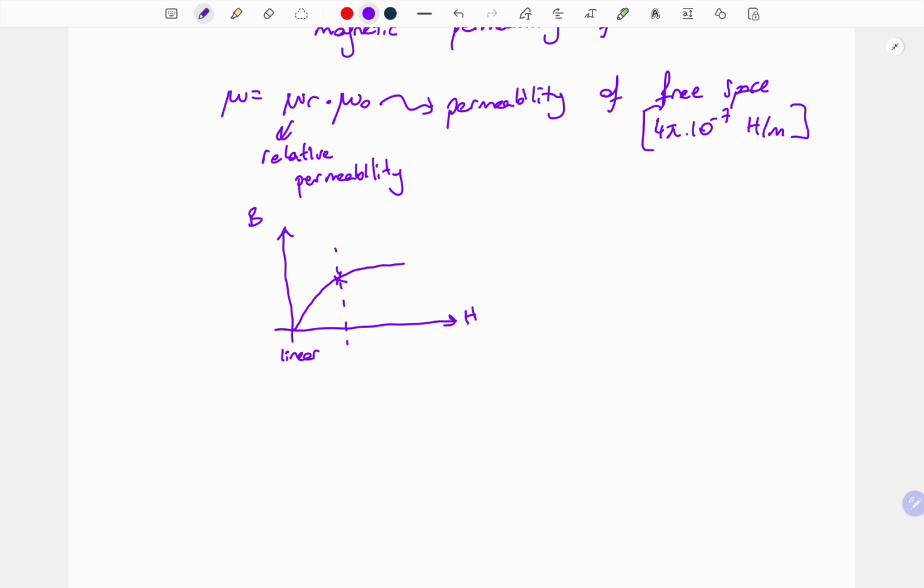That means the maximum potential magnetization has been applied to the magnetic core. So we shouldn't exceed this knee point during continuous operation, because after that we have the saturation part, and during that part the temperature of the magnetic core will increase. Because of this, we prefer to operate our magnetic core near the knee, but before the knee, during the linear part.